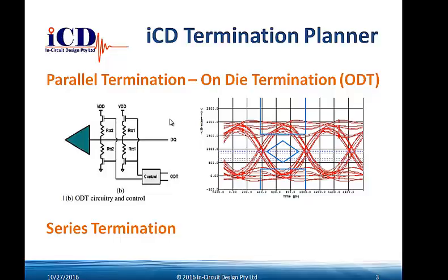So obviously if you're hanging a lot of these devices in parallel, well, then it creates quite a problem with simultaneous switching noise because you're exacerbating the current that's drawn. The one advantage of on-die termination is that it opens the eye diagram. So you can see on the right there the eye is wide open when you have the on-die terminations turned on, because it pulls the waveform up and down vertically and creates this open eye.